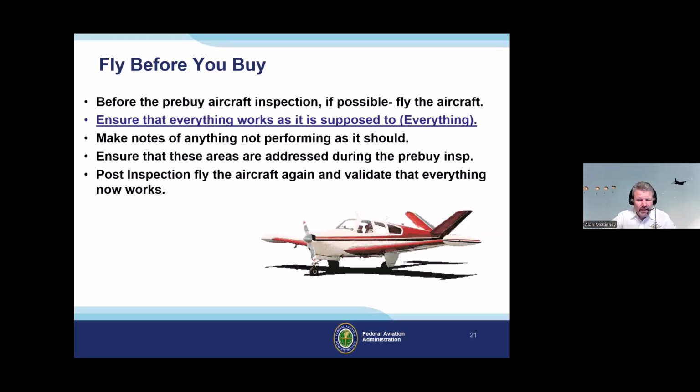And then you're going to have the mechanic who is working for you, not the seller, troubleshoot those and get an idea of what you think the expense will be. You can find out components and that stuff, but you want to know that. Then once the pre-buy inspection is complete, you're going to do that same flight after you're done. Because one, anything that didn't work initially should now work, and stuff that worked before should still work. You don't want any maintenance-induced issues, right? So you're going to check everything again.